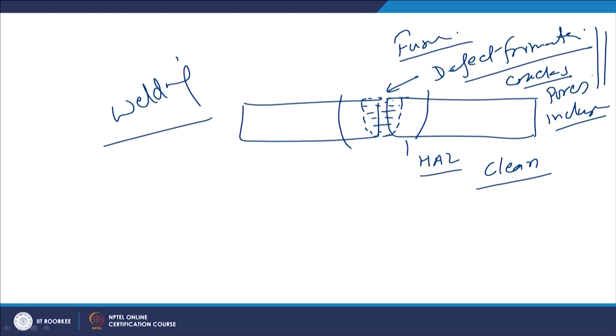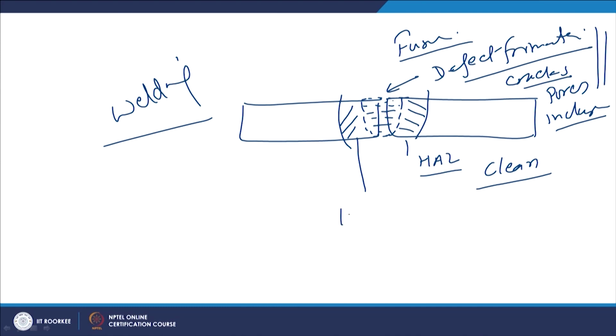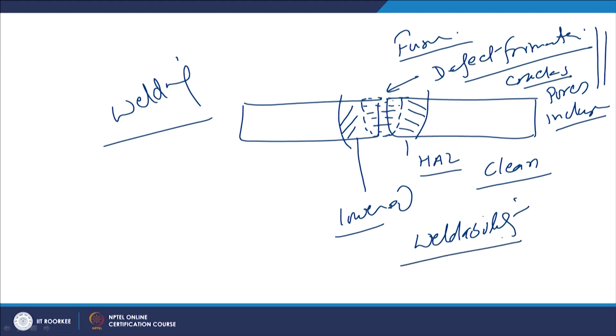these defects, but still there will be the formation of the heat affected zone. The way by which the HAZ properties are affected due to the application of heat for fusion welding significantly determines the ease of welding or the weldability. If there is significant compromise with the properties of the heat affected zone, meaning these properties are lowered, or the hardness is unnecessarily increased and the material is embrittled, then the weldability of the metal will be reduced significantly.